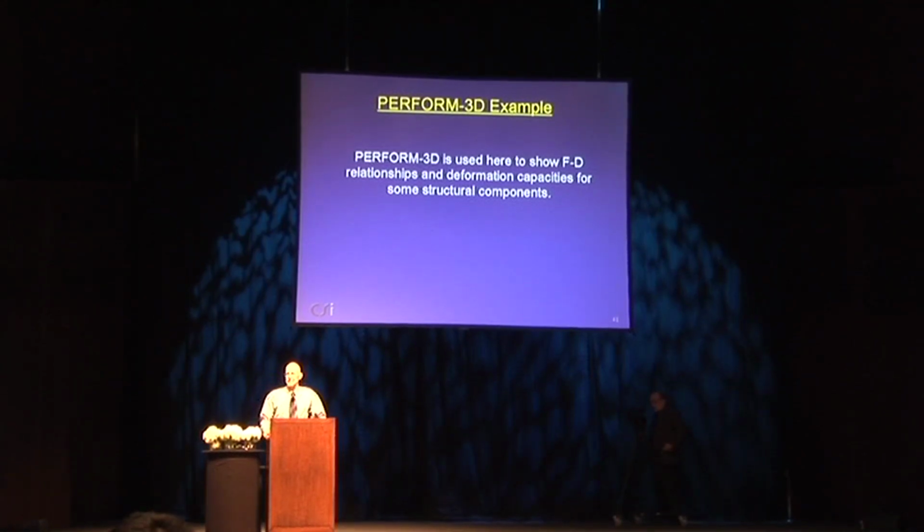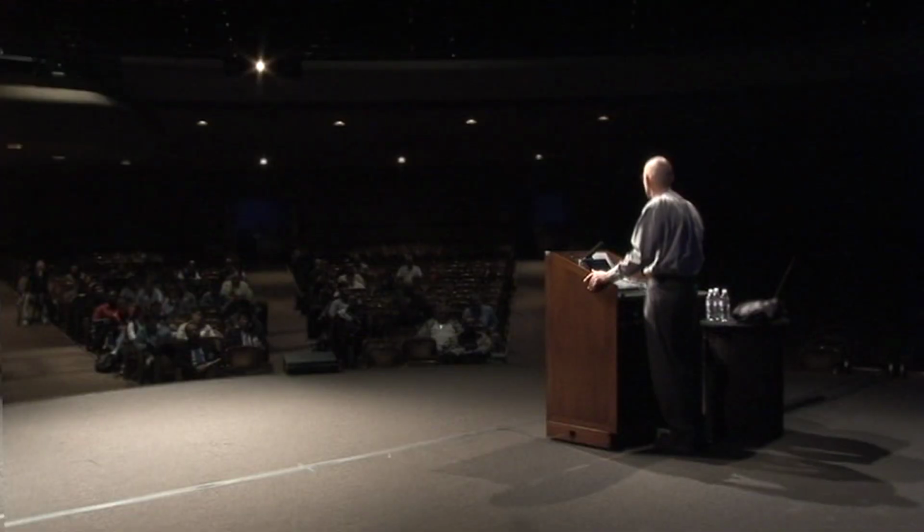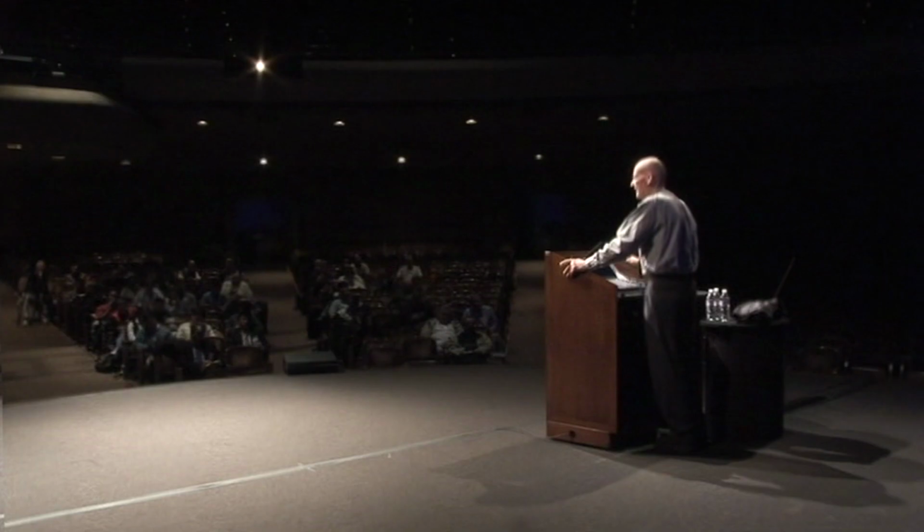When you're building a model, most of your time actually is going to be spent in that component properties portion of the input. Defining the geometry is relatively simple. Defining the nonlinear component properties is far from simple. In a linear analysis, it's a simple process. You just give material properties, you're done. Elastic modulus, maybe a Poisson's ratio, that's it, you're done. Nonlinear, no way, you've just begun.